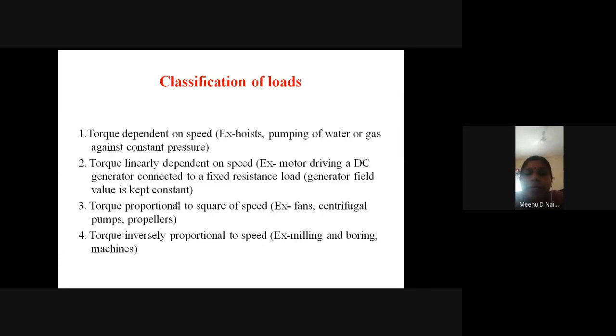Okay. So normally we have connected a load with the motor. Here two torques will be occurring: one is motor torque and another is load torque. The motor torque T and omega m, the angular velocity of the motor shaft, are in the same direction, and TL is in the opposite direction with respect to T and omega m. So considering the motor torque and omega m, I can derive the fundamental torque equation.